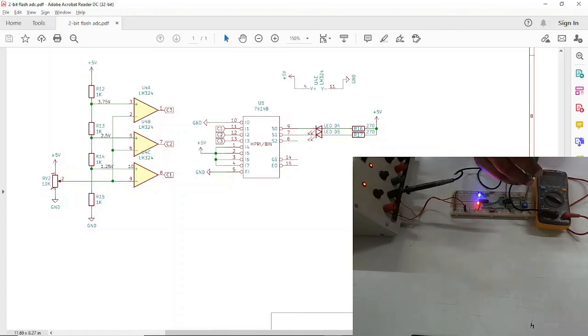If you want to accurately find out what the voltages are, you go through the first steps again. I made the input voltage 0.001. As I slowly increase the voltage, you can see we get an output state from 00 to 01. I'll change the input voltage slowly a little bit. Now it is 600 millivolts, 700 millivolts, 800 millivolts, and 1.185 volts.